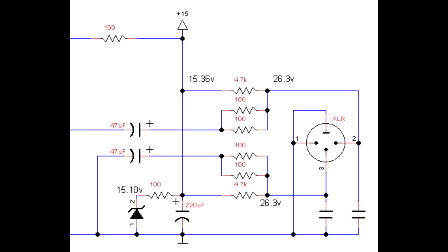Phantom power also comes in on pins 2 and 3. It's a 48 volt standard, plus or minus 4 volts. But you will have 48 volts available both on pins 2 and pins 3. The preamplifier will have a pull-up resistor to 48 volts at 6.8 kilo ohms. So you can't pull a lot of current with a microphone, but you can steal a little bit of power, certainly enough for a preamp circuit in the microphone.